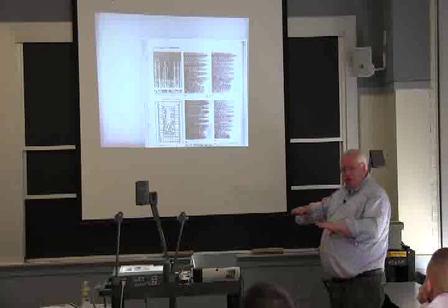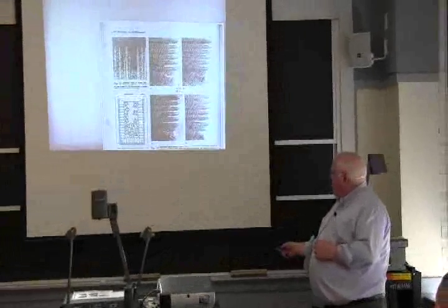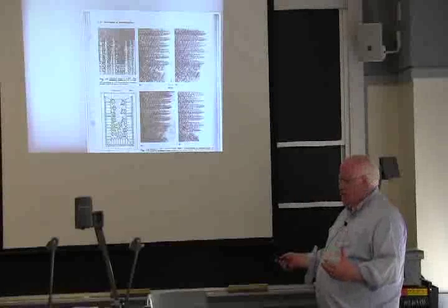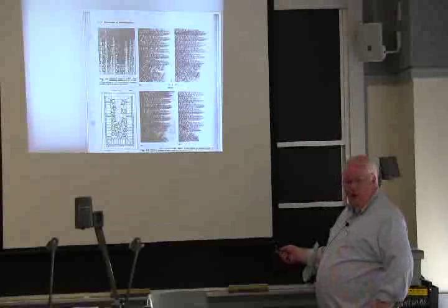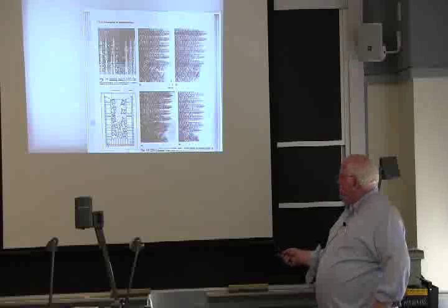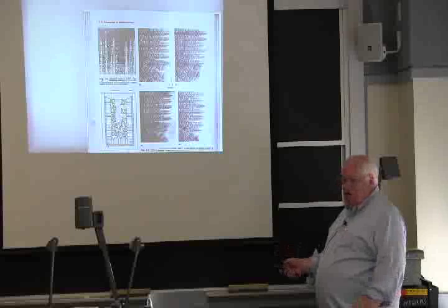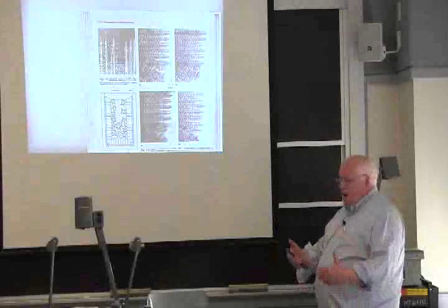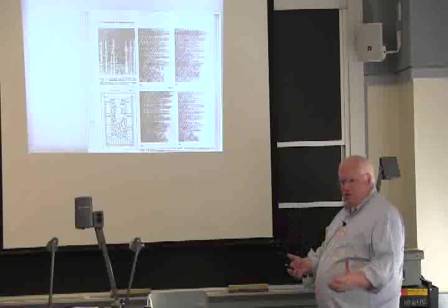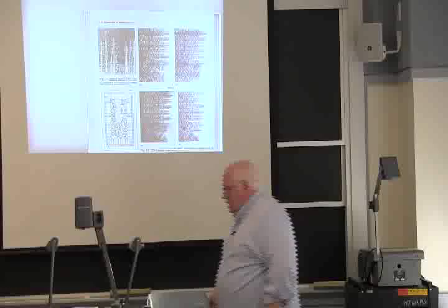And so we could get the best sheet properties from ingot cast steel, okay? Because the surface was very pure iron. The internal composition might be slightly different. You're going to roll it into sheet, you don't really care. But in plate, you didn't want that. So we have to worry about how we solidify these things. But as the fluid flow goes on here, it's due to differences in buoyancy, and part of that buoyancy is the composition differences. I got molybdenum, which is very heavy compared to steel, and in an iron molybdenum alloy I can get tremendous segregation because of the differences in densities of the different elements. And that's what we call macro segregation.